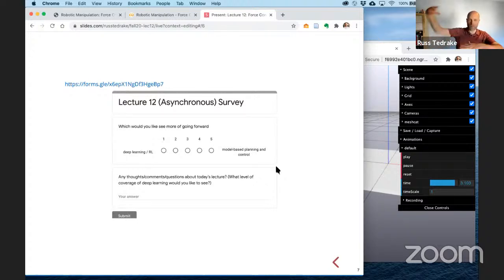So I think it is principled in the sense that back in that day, we probably put the book in some initial configuration, and we came down roughly on it. Once we were in contact, detected by the force sensors, we pushed down some threshold amount, and then drove through a prescribed trajectory: lift it up, put it down, and a prescribed trajectory to push it off.